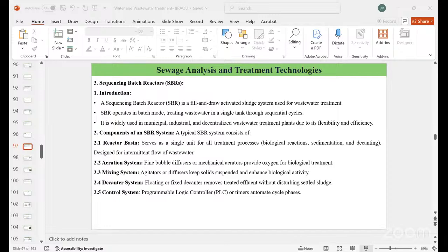And there are mainly applications for the removal of emerging contaminants, treatment of industrial wastewater, disinfection processes, drinking water treatment, and all this. Other advantages include that it is effective in removal of recalcitrant pollutants, it has high oxidation potential, and it has minimal sludge production. The main disadvantages are high energy consumption, capital cost, and byproduct formation. And the considerations can be addressed by doing process optimization. That is, factors such as pH, temperature, and contaminant concentration must be optimized for efficient AOP operation.